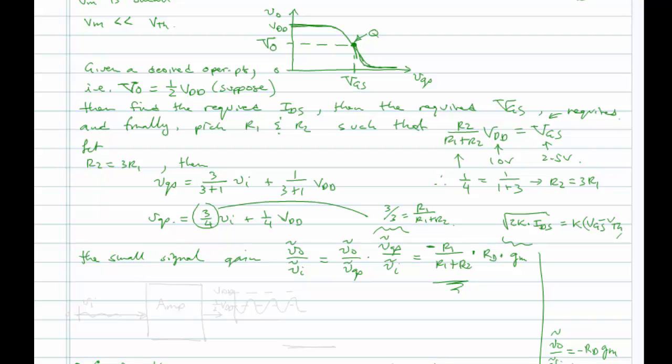So what have we shown? We've shown that if I put in a zero offset signal into an amplifier, okay, here's my amplifier, this type of amplifier, and this is ground here, VI, then what I have coming out will be, this is VDD, I will have it biased at half VDD because that's what I requested, but it'll oscillate around 1/2 VDD.